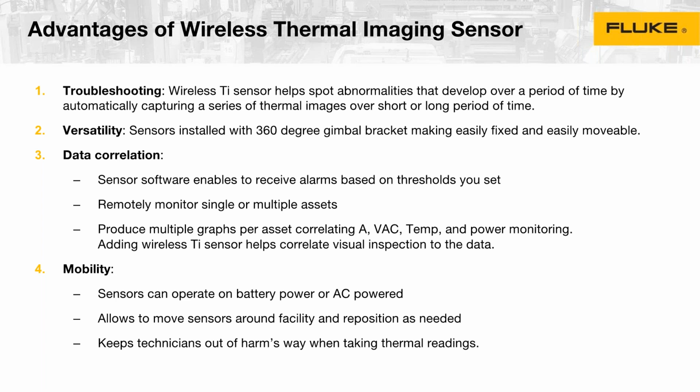The versatility, which is really how easy it is to move, relocate, and install this. I think for me, one of the big factors really is the data correlations. I talked a little bit about this in the example about the vibration and the thermal imager, where one of our customers found the issue to be electrical, not vibration related. We should see either the thermal, the vibration, electrical testing, or sometimes oil analysis, volts and amps. Anytime you take one of the measurements, it really is a great rule of thumb to not use that particular parameter as the only decision factor.